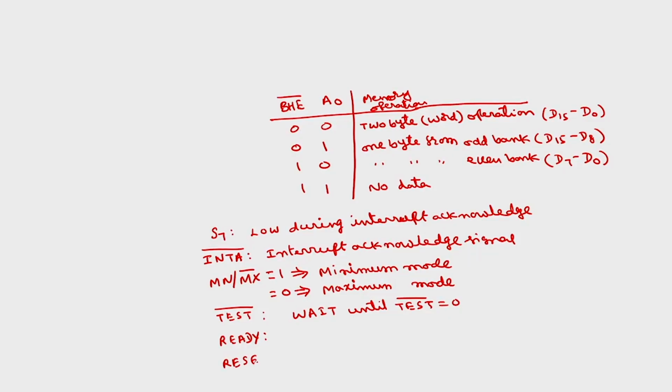Whenever the microprocessor is reset, it will suspend all the internal operations. It will make the stack segment, data segment, extra segment, instruction pointer and flags 0, and the code segment FFFFH. So, whenever this reset is removed, the next instruction to be fetched will be from FFFF0H, which we have already discussed in the last class.